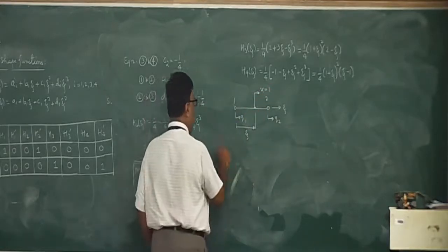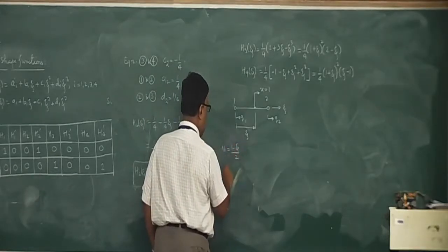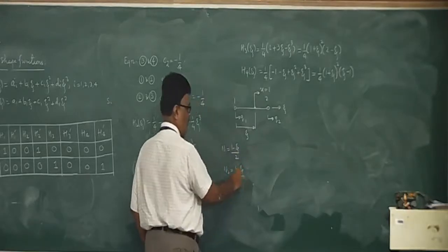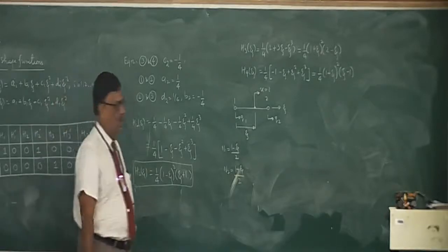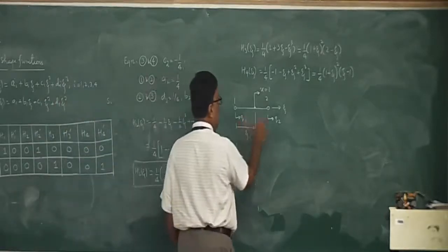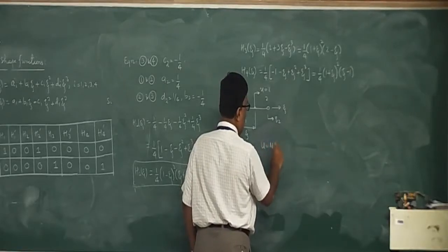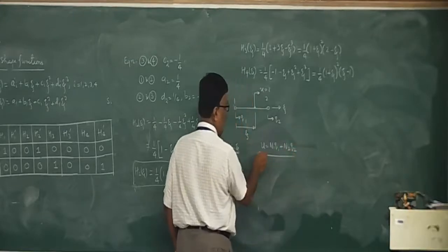So naturally we had defined 2 shape functions there. We called them N1 and N2, as 1 minus zeta by 2 and 1 plus zeta by 2. And then by knowing these nodal displacements Q1 and Q2, what we had found out was N1 Q1 plus N2 Q2. This is exactly what we had found out.